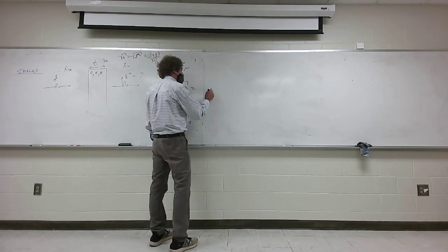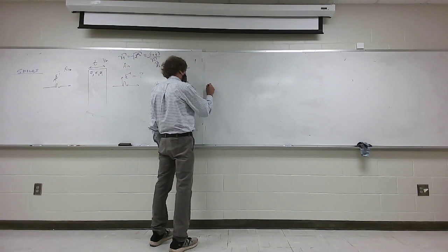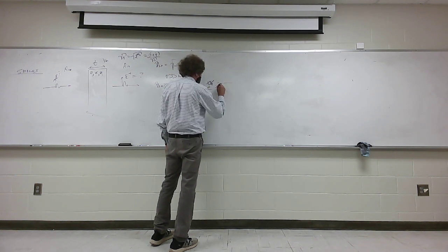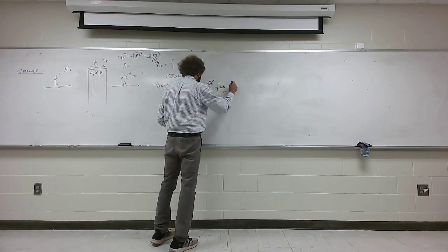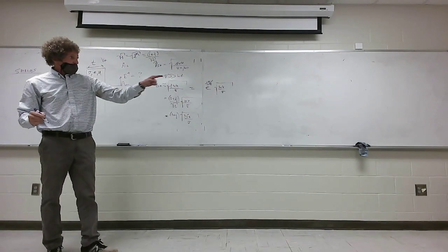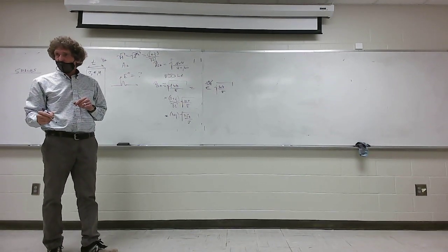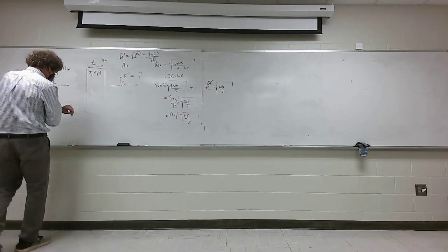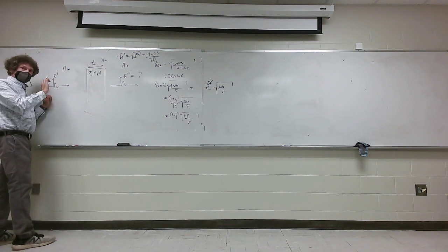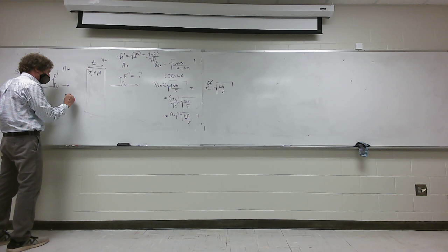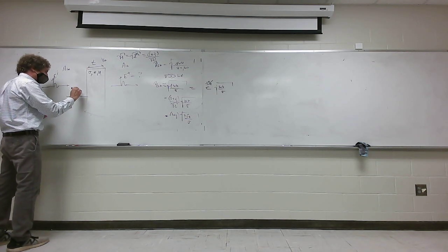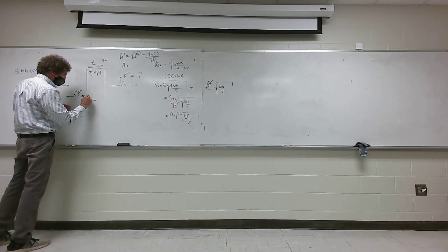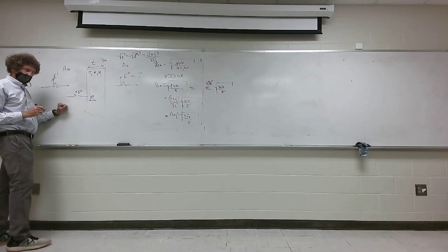Probably the most common way to write this is e to the j pi over 4, or 45 degrees, times the square root of omega mu over sigma. All of them are correct. That's probably the most common one because the angle is pulled out right there. Now, that said, we start going through what you need to calculate. On a problem like this where a signal is coming, some is scattered back, so we have some E reflected here, correct? Some is transmitted, and I'll call that E transmitted 1.